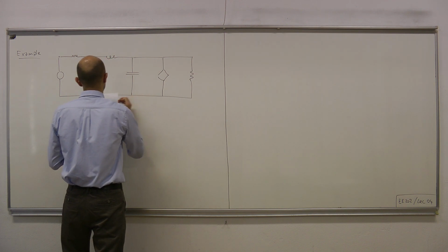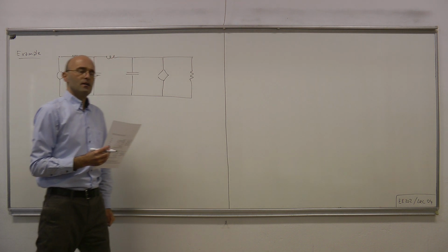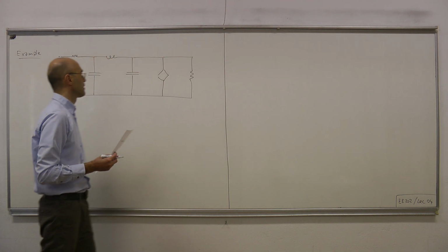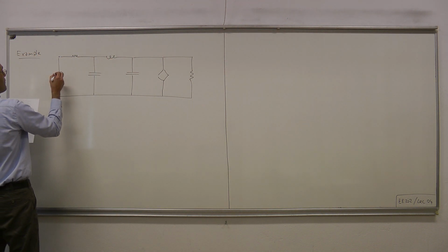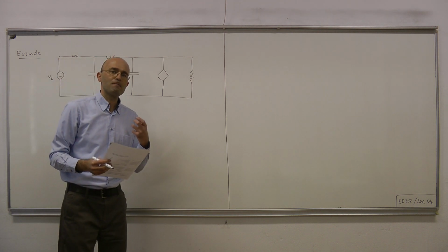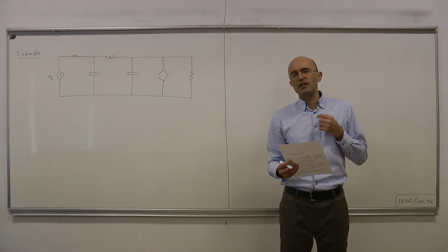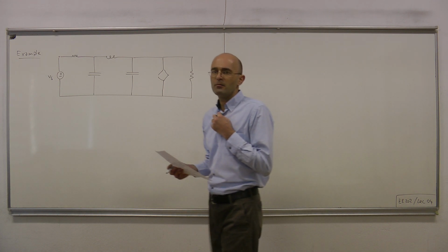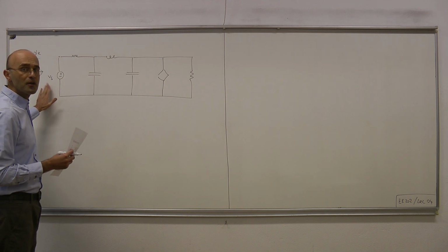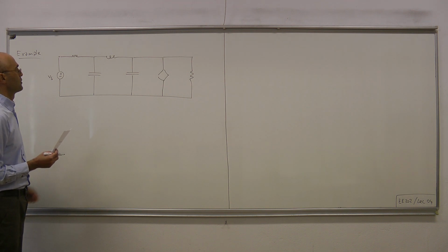So it's a third order circuit because we have three dynamic components, two capacitors and one inductor, whose initial conditions we can pick freely. We have a single input in our system. Remember that by input or inputs we mean the voltages supplied by the independent voltage sources and currents supplied by the independent current sources throughout the circuit. So in this circuit we have just a single independent source, this voltage source. Therefore it's our only input.